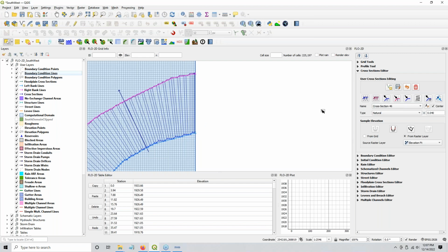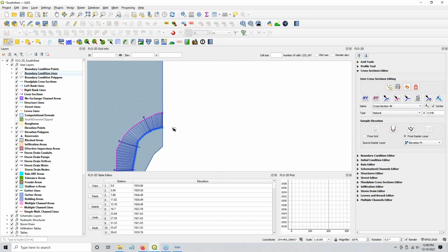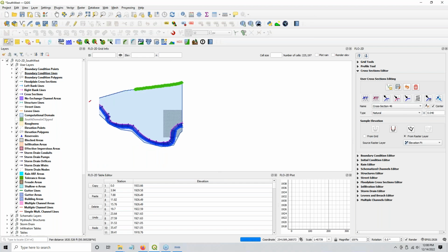And again, when the water is moving through this system, you are going to lose that momentum at this boundary. So make sure to make this boundary at a location where you're okay with that. Boundaries are kind of sacrificial areas. So the water will take a bit of time to fill this back up before its momentum and velocities and everything kind of build back up in the right direction. But since you start at 0 discharge, everything goes fairly well organized as it crosses the boundary.